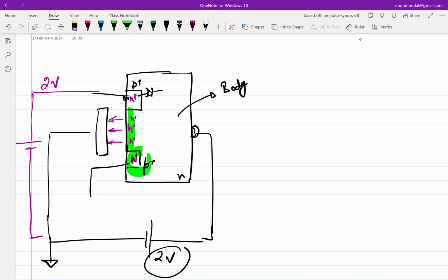Okay. So now if I apply an electric field from top to bottom, it is expected that the holes will flow from the tub on the top to the tub on the bottom, and this channel is going to control whether the holes can flow or not, because the electric field that is forming inside that dielectric, which is air in this case, is controlling the concentration of holes in the channel. It's like the valve of the tap.